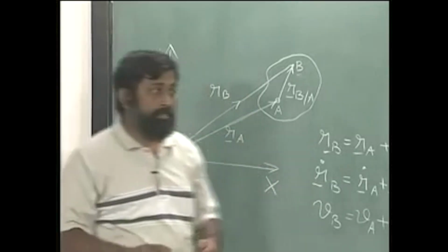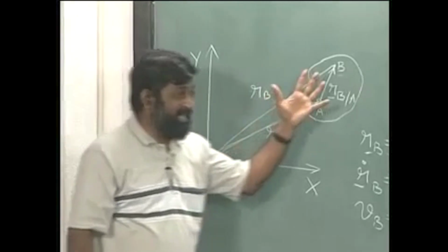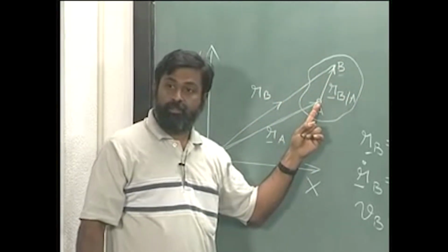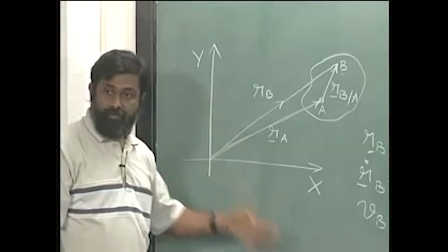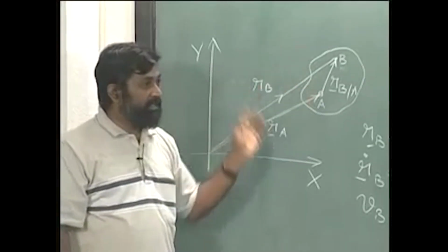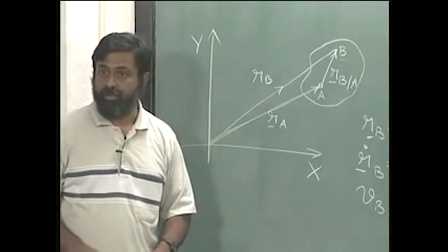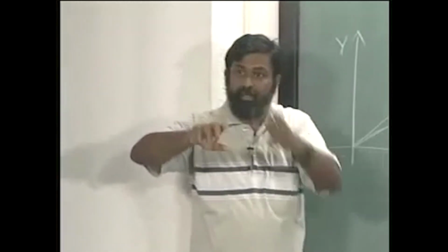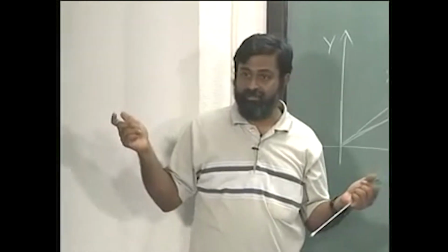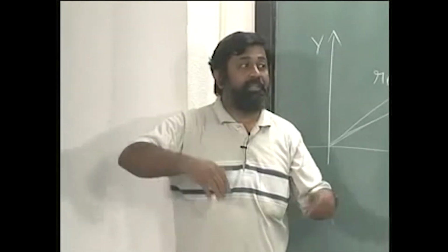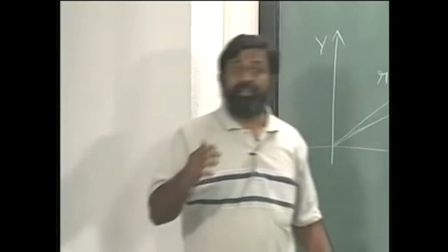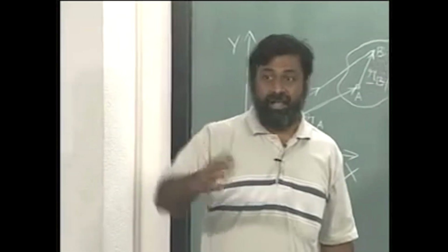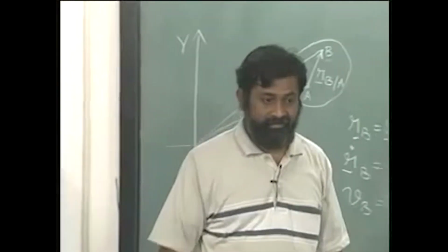Now, supposing I know in this current position one of those points with respect to a fixed frame, and I know there is a rotation that is occurring on this rigid body, every point on this rigid body will be seeing the same rotation. If it is seeing the same rotation, it will also see the same rate of rotation and a double rate of rotation, alright.